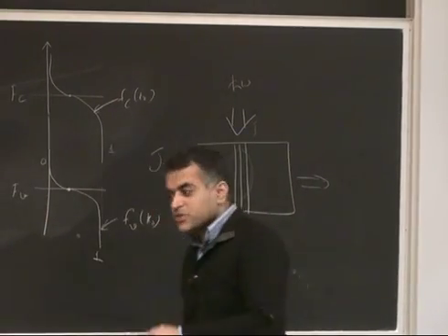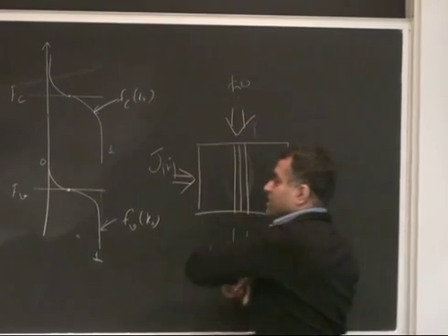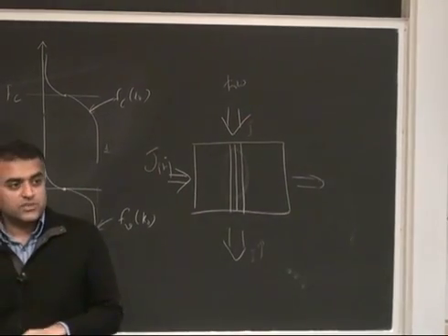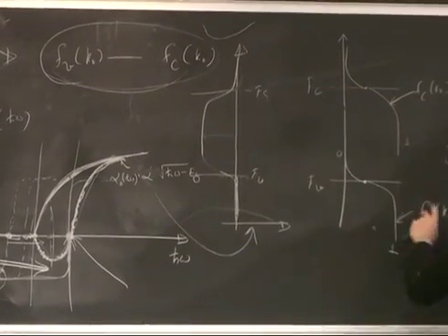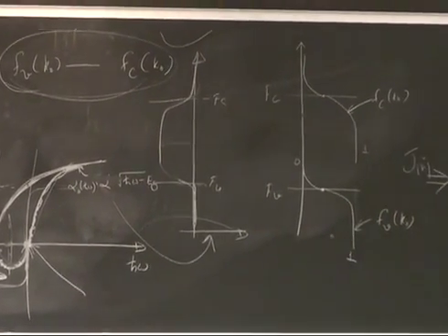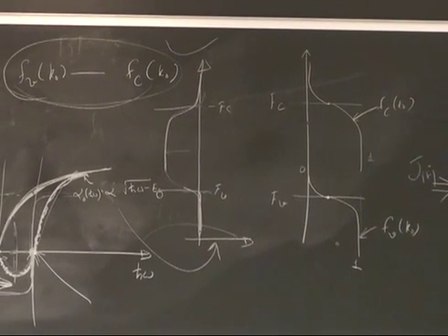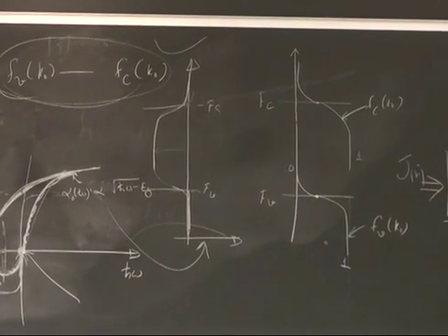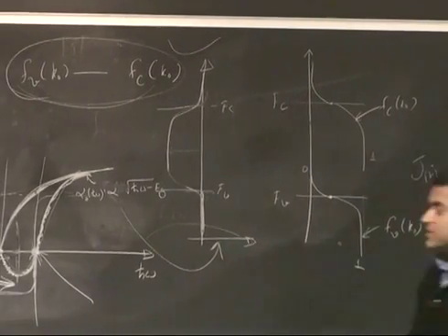So what you did is you took a semiconductor. If you had not applied the voltage and you pass a photon of this energy, it will get absorbed very fast because it's larger than the band gap, right? But now you turn the voltage on, and this light will go through. So it's some sort of a switch in some sense. By applying a voltage here, you let light go through or not go through. Right? So that's kind of an interesting aspect of this.